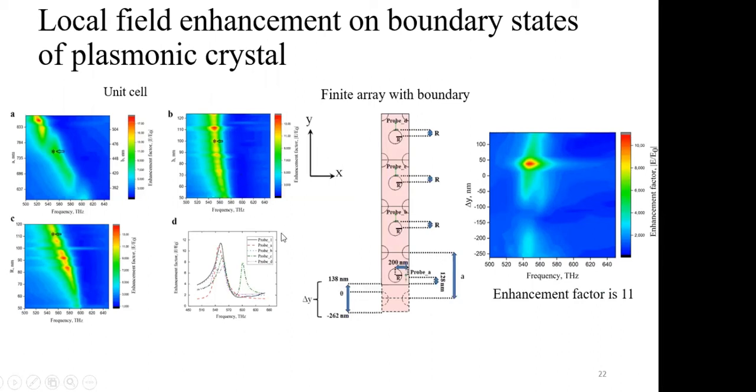It was interesting, and as you see here in the green laser, the structure was designed based on a unit cell, and we add some probes to measure the electric field on the surface of this structure. Enhancement factor was measured, and for each probe which we make a distance from the gap which I showed you, you can see the electric field enhancement decrease.